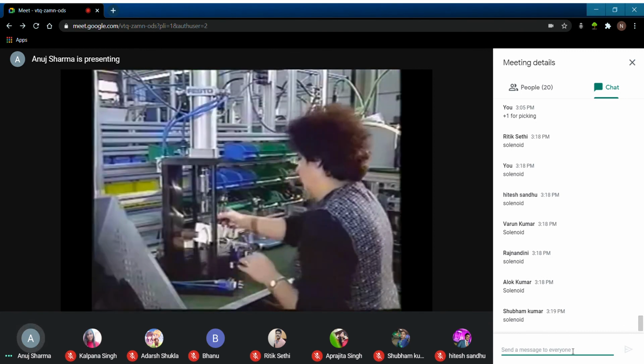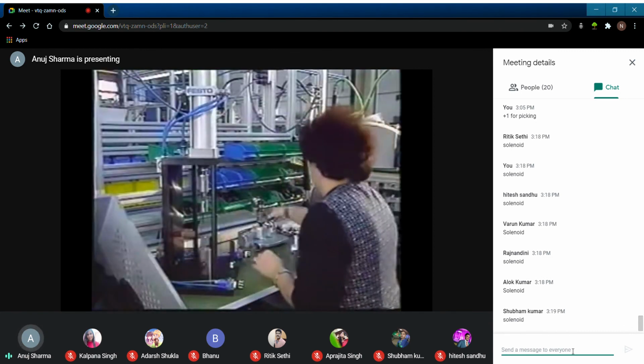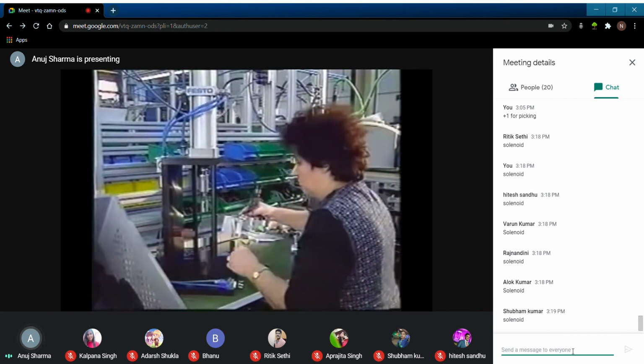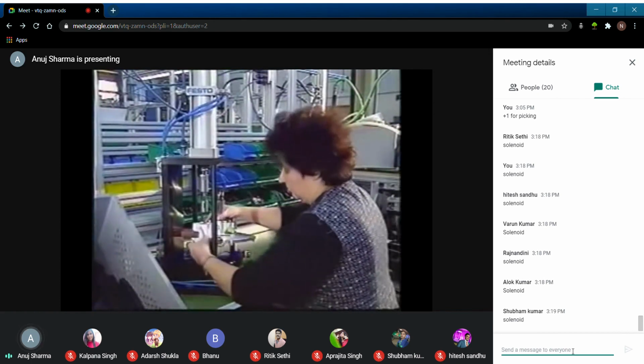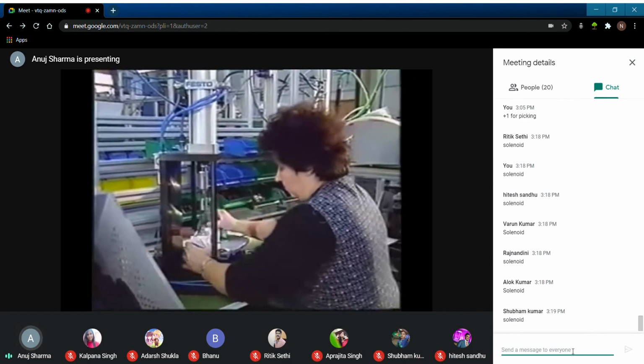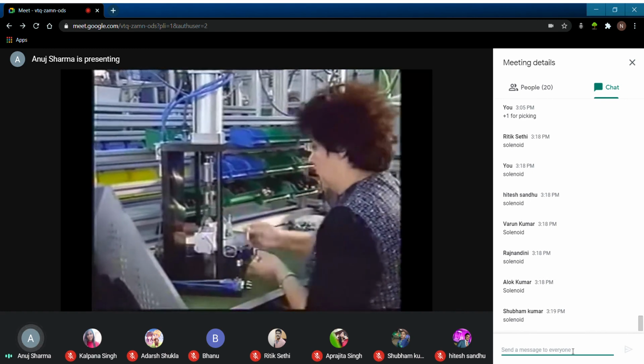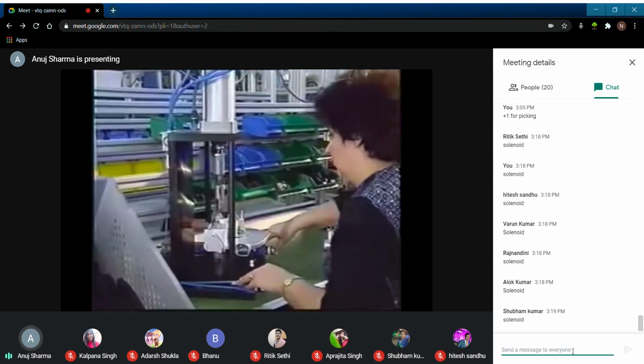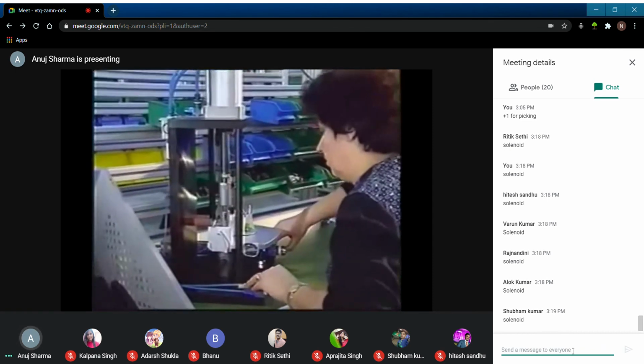In this machine, signal input is provided by the machine operator. As long as the operator presses both push buttons, the cylinder continues to extend. When the operator releases either button, the cylinder retracts. Therefore, the cylinder movement is manually controlled by the operator.